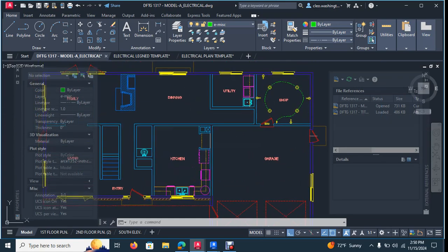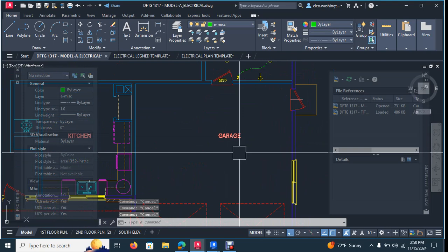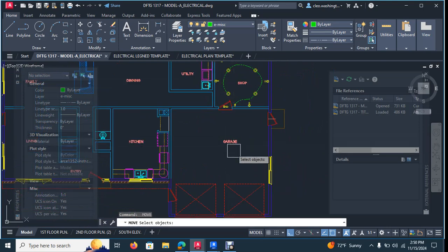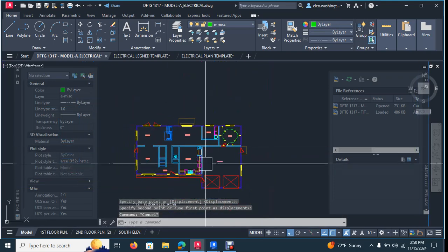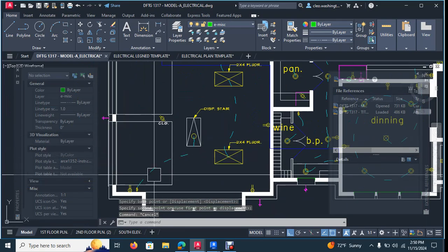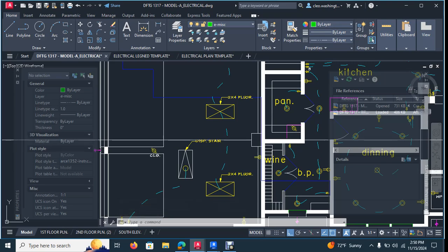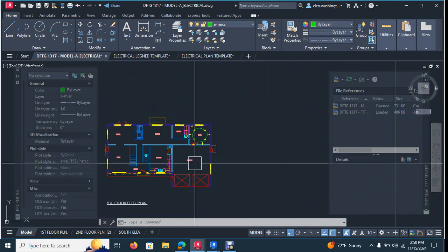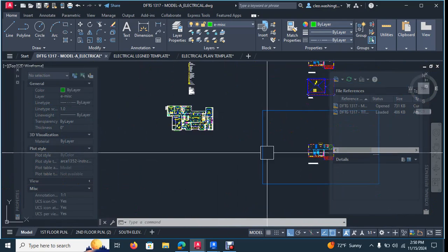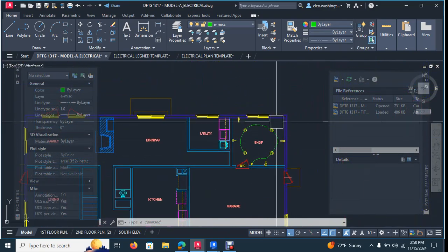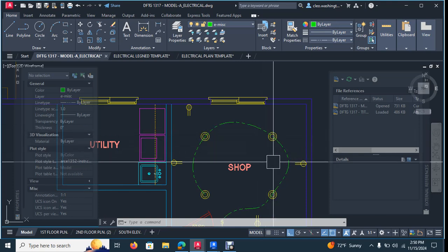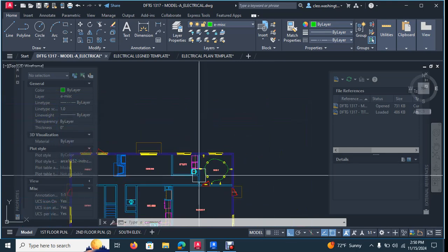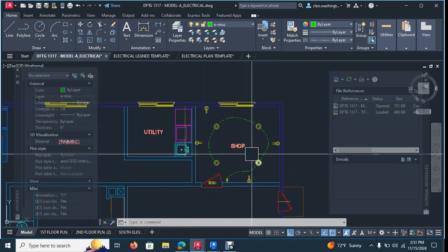So I'm probably going to do, let's go ahead and do the garage. That's going to be a fun one. Because the garage, they have specified things and things of that nature. Typically, in the garage, you'll have some type of attic access, so we'll show that in. And actually, what we're doing is we also are creating what's known as an RCP plan. That's basically your reflective ceiling plan. That's why we turn everything off, because essentially you're looking up at the ceiling.